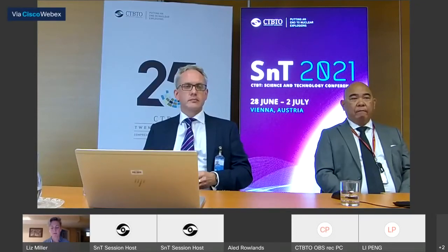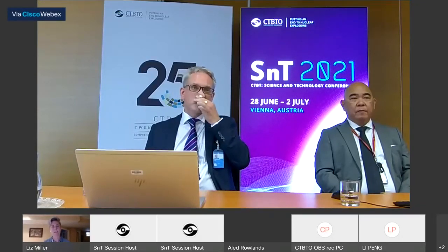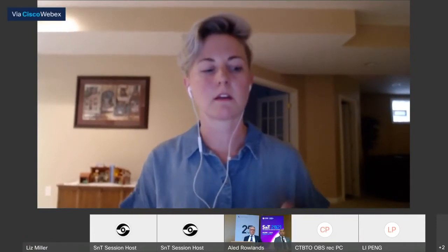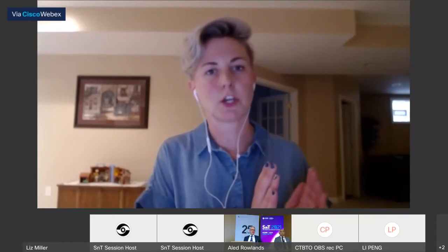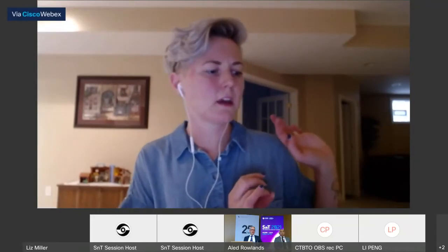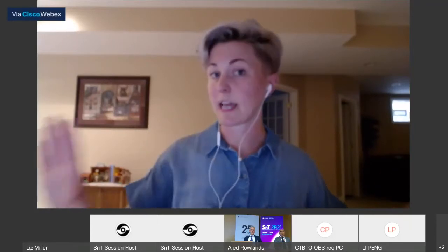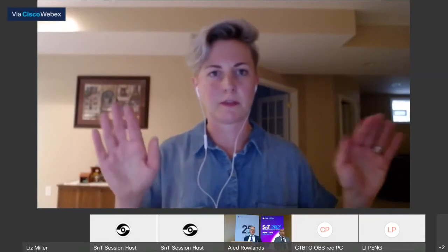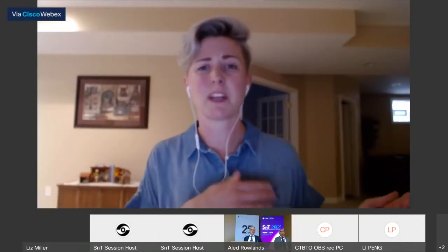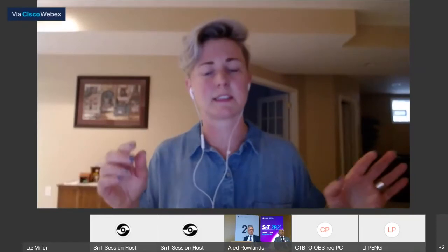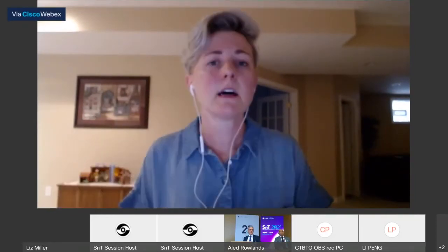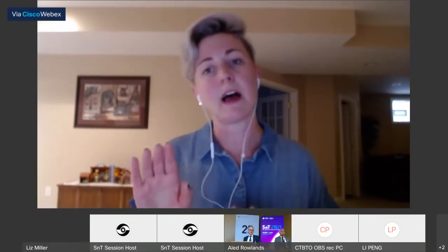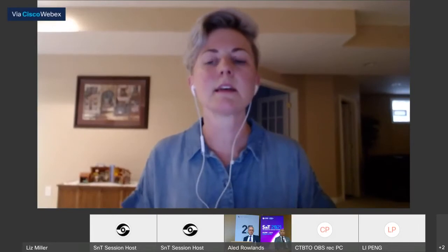Yeah, so the one thing that I should caveat just a little is that where it starts to get a little tricky is that we haven't built in the ability to go from, let's say you had a 30-meter resolution data set and a 10-meter resolution data set. There of course would be some issues there with pixel size and resolution, and you would get a lot of false positives just because of that resolution difference. So what we haven't built in yet is a step that would essentially resample everything to the same pixel size.